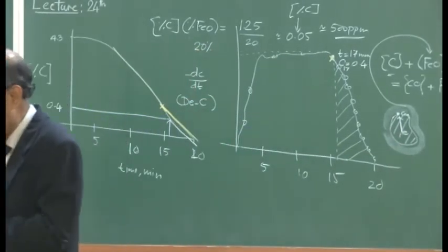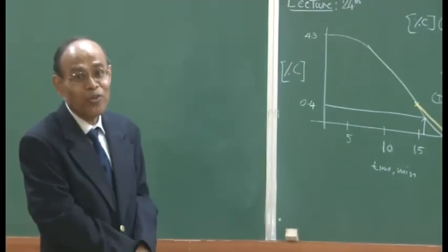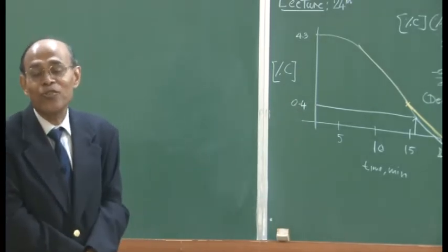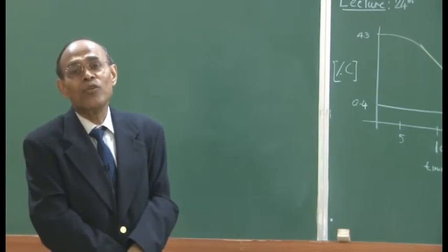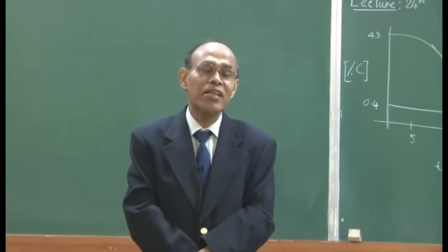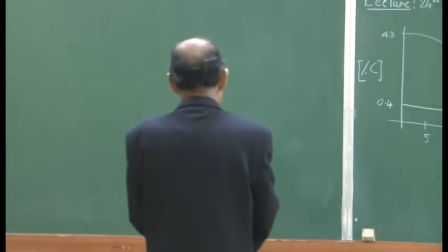So, the kinetics are going to be different, and we know that our processes are mass transfer controlled, not chemical reaction controlled. Had the processes been chemical reaction controlled, the introduction of oxygen into the system would not matter. It would matter only whether we are injecting partially impure oxygen versus pure oxygen, and so on and so forth.